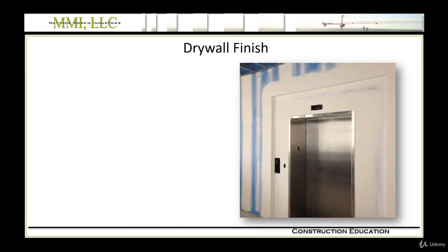So now that the drywall's on the wall, the finishers move in to tape and finish the drywall. They first apply joint compound in the joints, and then they set tape in that joint compound. And the joint compound is typically gypsum mixed with water to form a mud, which is applied at joints and also at screw locations. It hides the joints and ideally will eventually provide a flat, seamless surface for the future painter or whichever wall finish is chosen.